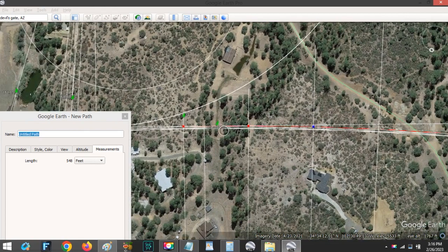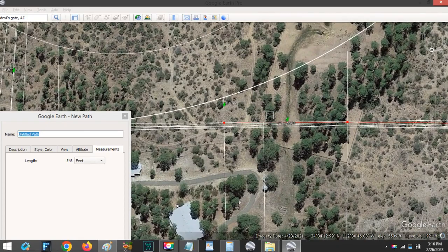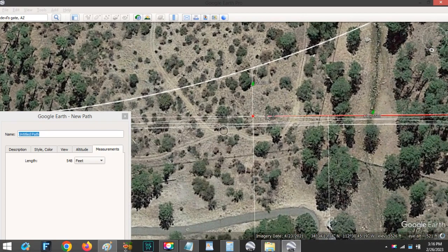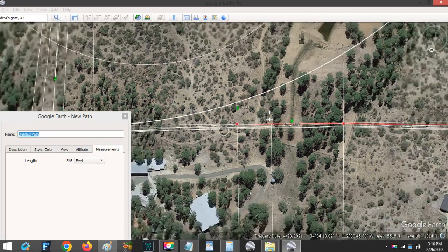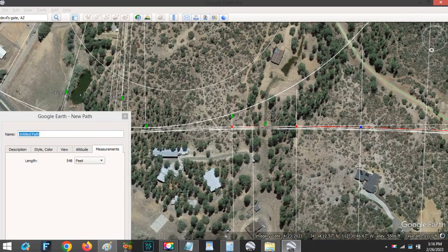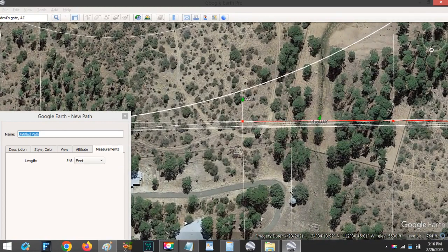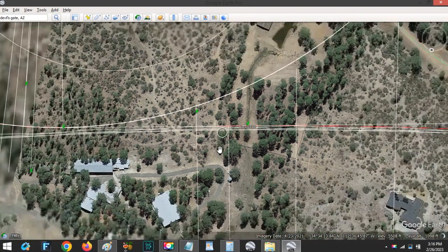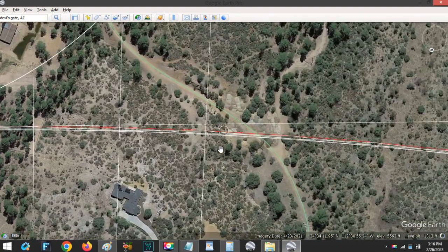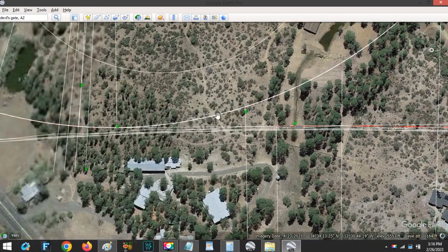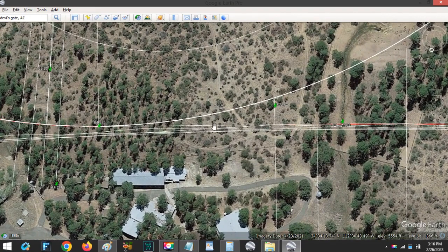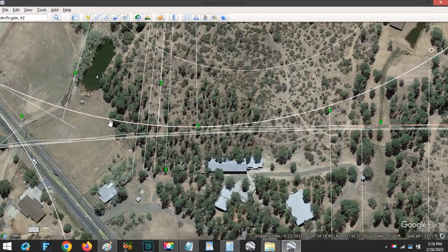usually they have an offset on the side or both sides that they want to spiral, and say this is 2,500 feet, you'd have an offset of 12.5 feet, so the circle would be down here somewhere, and then you would start the spiral opposite the curve and run it out to way beyond the curve on the tangent, except we don't have much room to do that here because our next curve starts right away.